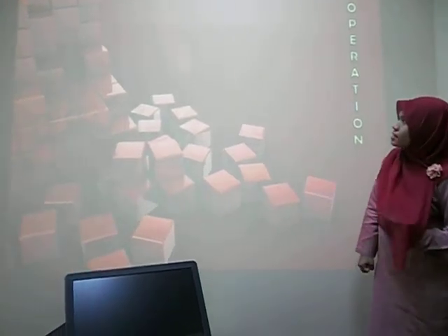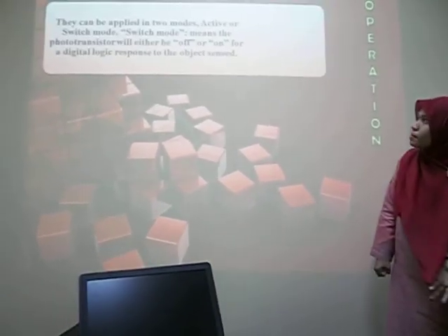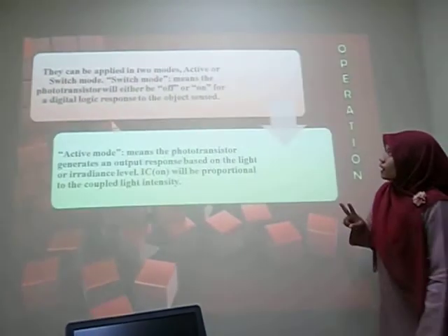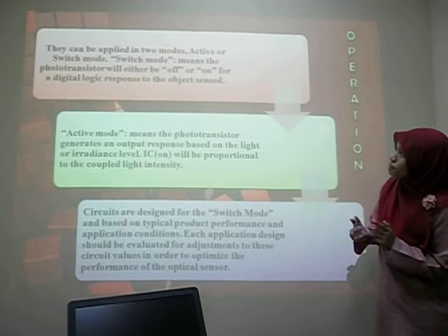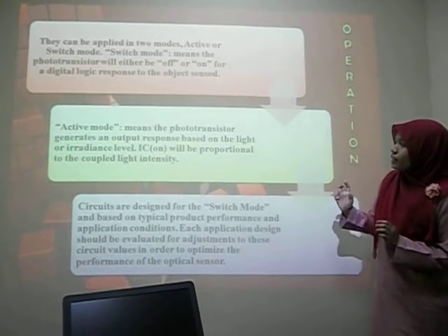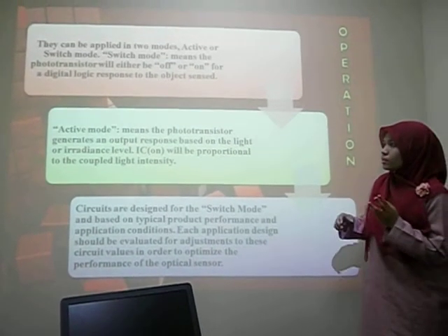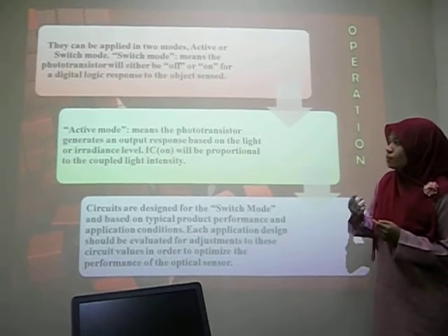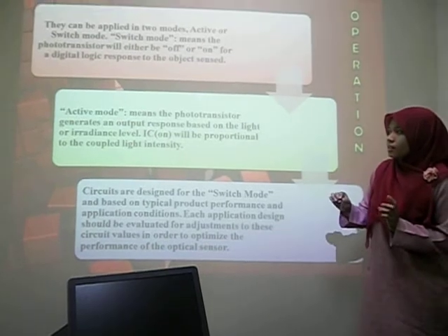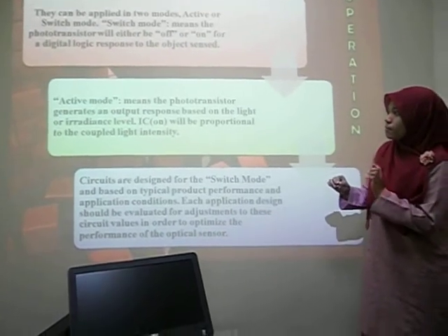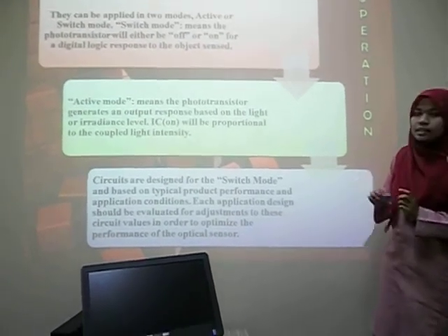Next, they can be applied in two modes, active or switch mode. I will explain the active mode. Active mode means the phototransistor generates an output response based on the light or irradiance level, which will be proportional to the coupled light intensity.